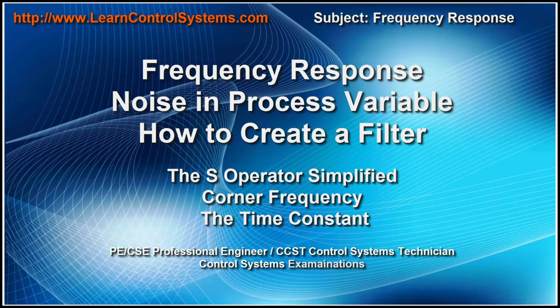Okay, frequency response is how quickly something moves, like how quickly a valve will move, or how quickly a motor responds, or how quickly a tank level responds, or a flow level responds. And with the process signal coming back that feeds us the signal of what the process variable is, typically there's noise in there. And we want to see how to remove this noise in our process variable. And we'll look at this in a fair amount of detail here.